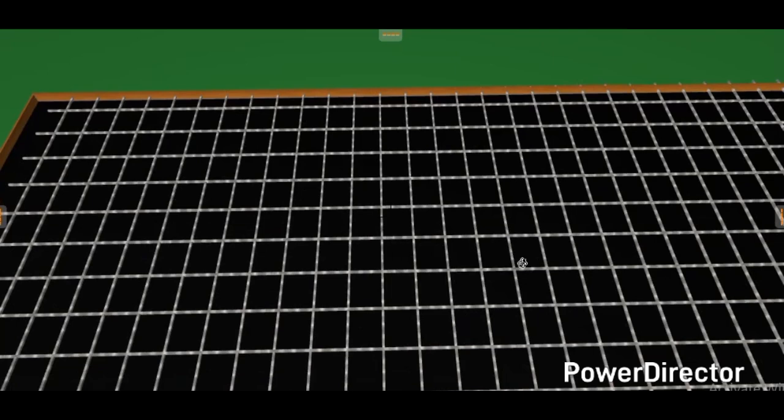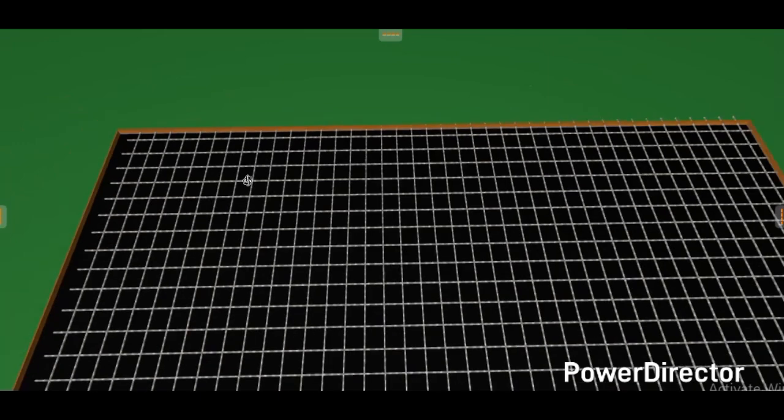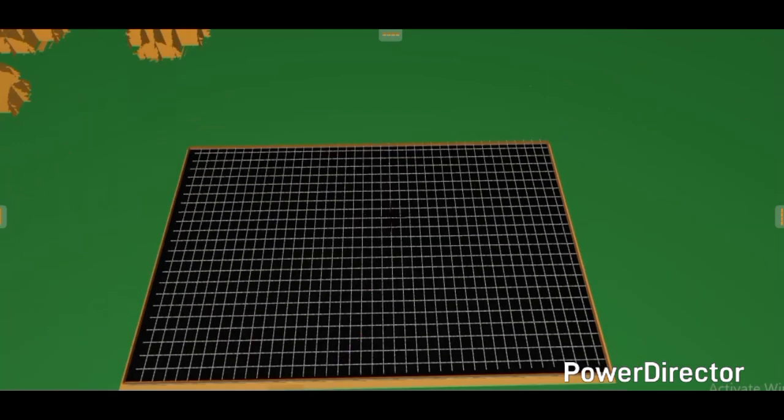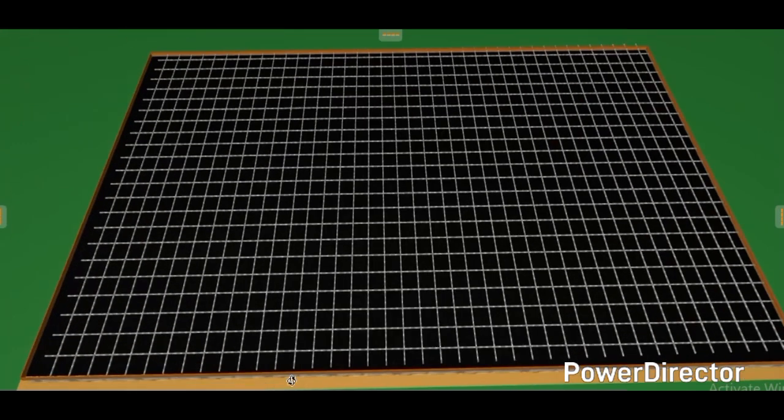Of course, I have not demonstrated how the spacers from the downer part are placed, but in general, you can understand how the BRC mesh ref 198 is being placed before now pouring the in situ concrete to have it strengthened by this BRC mesh.